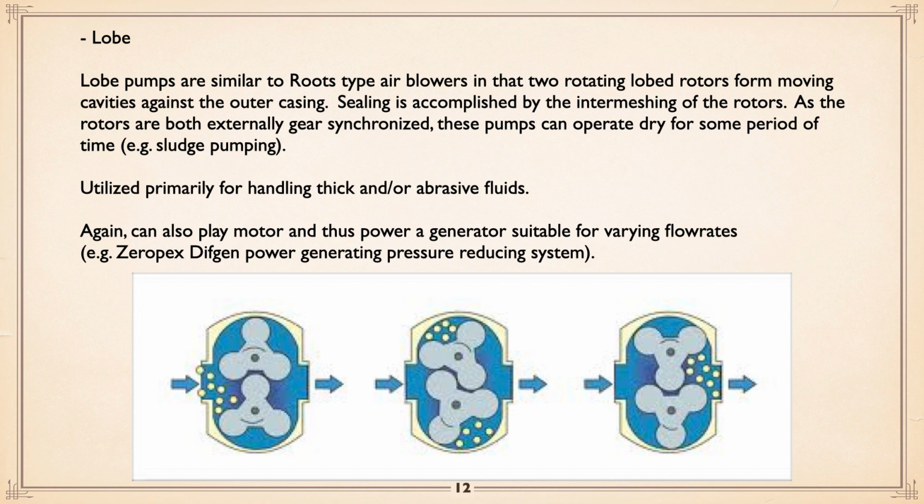And I thought, I don't think so, because as you already know, centrifugal or kinetic pumps don't like the extremes of a curve. But it turns out they weren't using a kinetic or centrifugal pump. They were using a lobe pump like this, which of course can go down to very low flows because it is a positive displacement pump. Now, there's the name of the company. I don't know where they are now, but if you ever get into something like that, there's a lead.